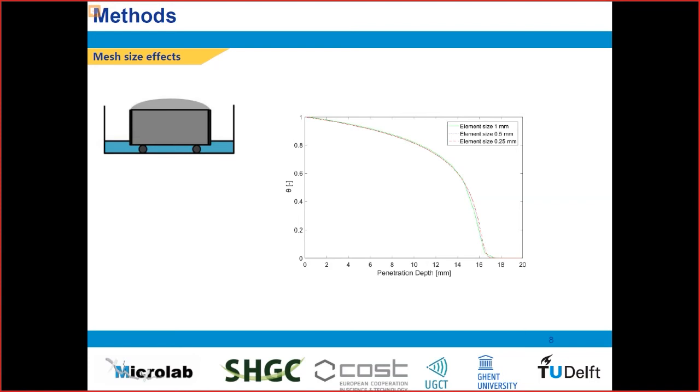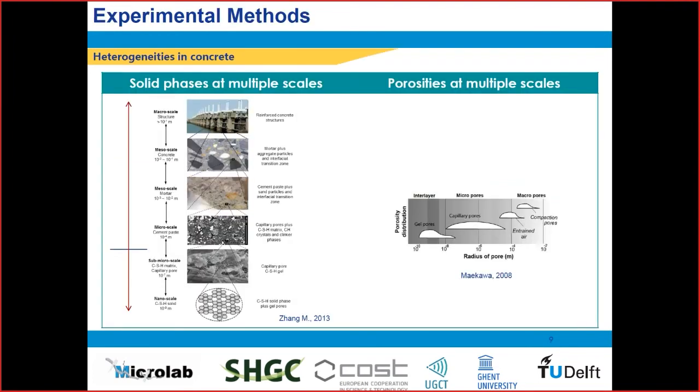Precisely about this last part regarding the validation of the model, we designed an experiment that helped us to do so. These experiments involved X-ray computed tomography to monitor the distribution of moisture during capillary absorption of both sound and cracked mortar samples. This experiment was done in collaboration with the geology and physics departments at Ghent University. Now I will devote a little attention to the methodology that we use for carrying out these experiments, before comparing the experimental and the modeling results. So, a little break from modeling, here it goes.